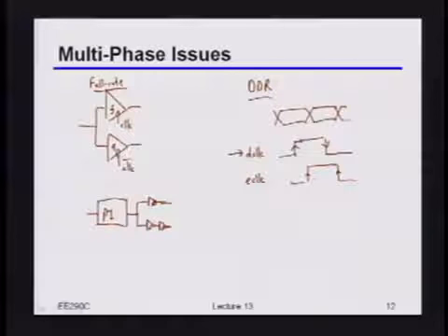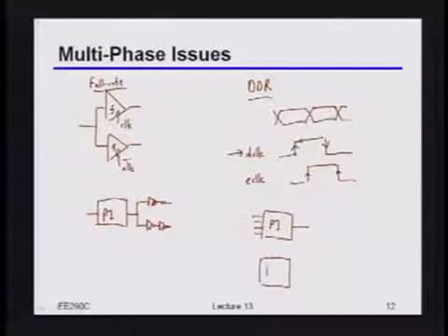And you just interpolate from the phase interpolator again? Interpolate from the phase interpolator. What exactly do you mean? What I mean is, can you use the same 4 phase inputs and generate the edge clock also? Yeah, absolutely. So you could indeed. I've got 4 phase inputs into that phase interpolator, giving me 1 output. Well, I could just copy the phase interpolator, take those same 4 phase inputs, but rotate the code by 90 degrees, right?